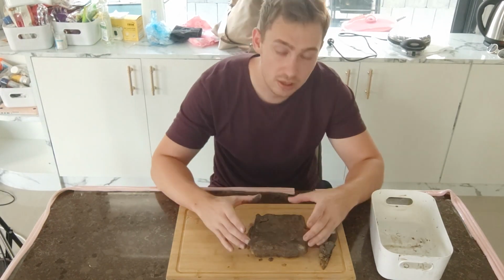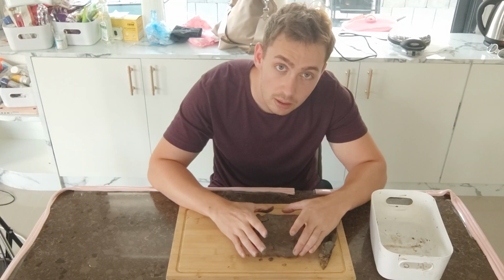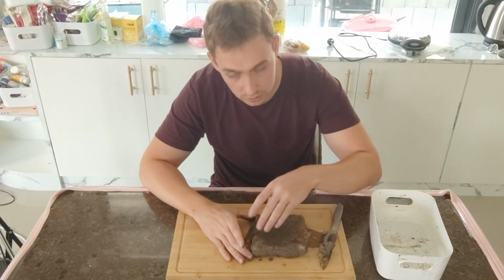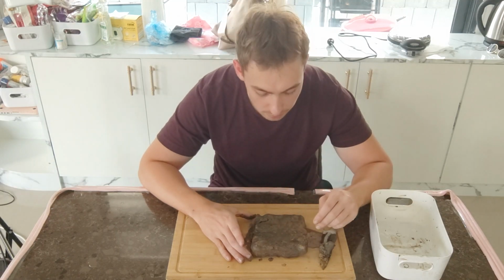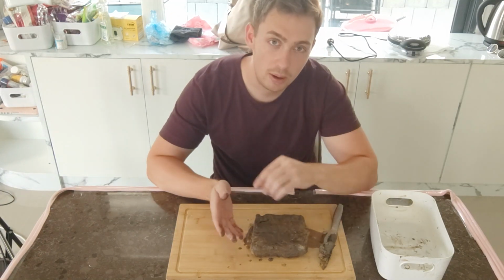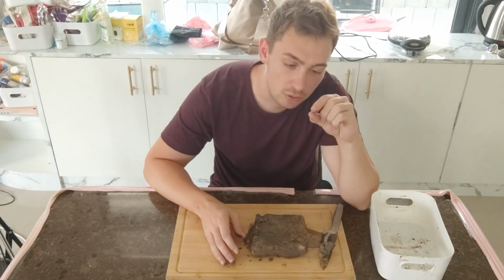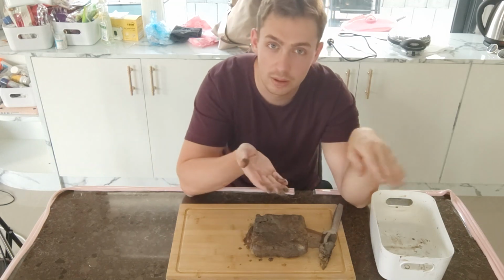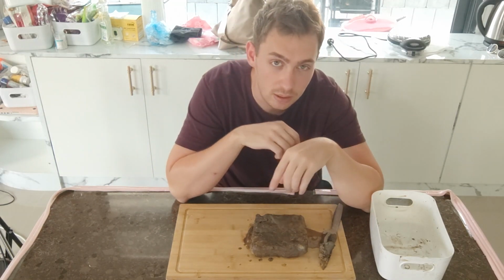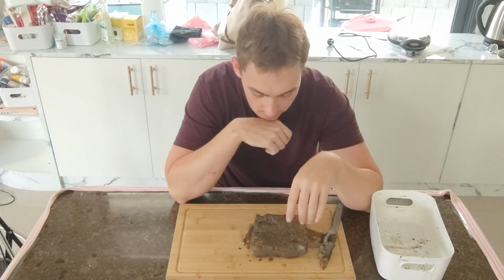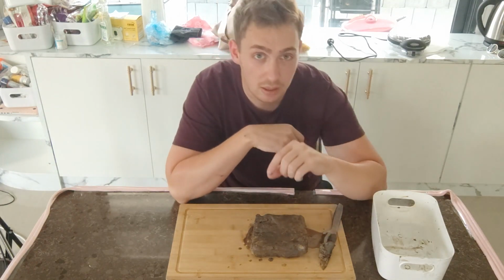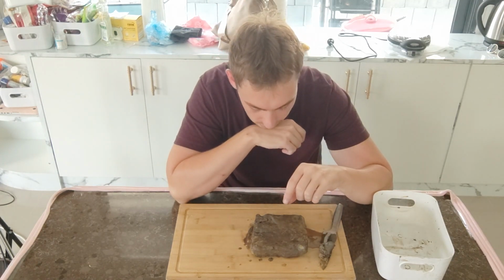Well, then the machinist has to clamp it down, and he has to machine all the way around. He could also just do the sides and then bore in the middle. But if you are at that point, you would normally just go all the way around, and then you would turn around and clamp it with about 2 millimeters at the bottom. So you turn it around and then remove a little bit of thickness. So you should actually order this one in bigger sizes. Let's say this one is 100, and then it's 30 thick, 30 millimeters, we're talking millimeters always.